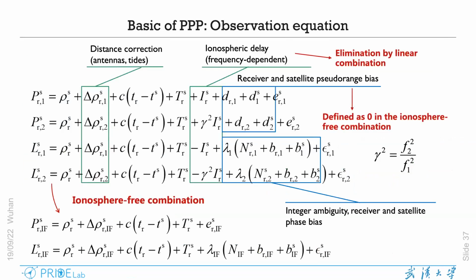All right, so after we finish all of the introductions of the errors within the GNSS observations, we come to some very, very complicated equations here. But actually, you can see some similarities between each line of equations. Here we have the geometric distance measurements between the satellites and the receivers, and we have the clock errors here, and this is troposphere, and this is ionosphere, and we have the code bias and the phase bias here.